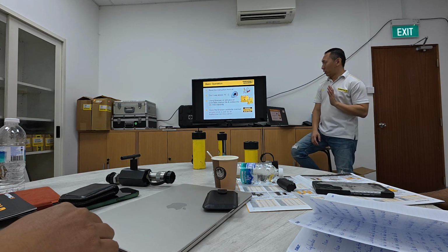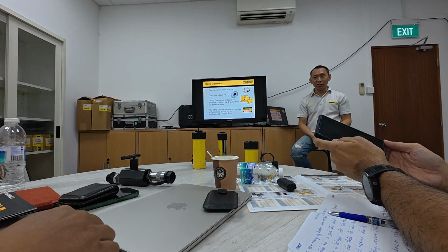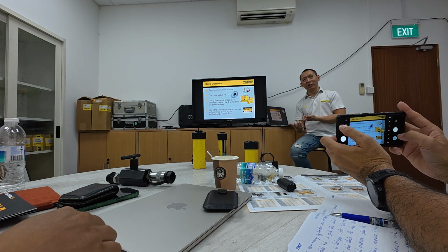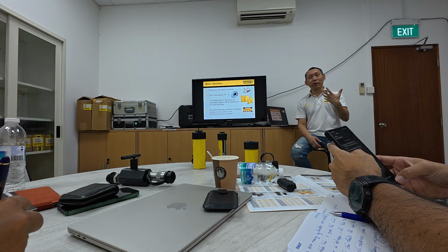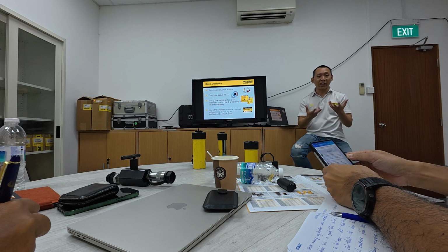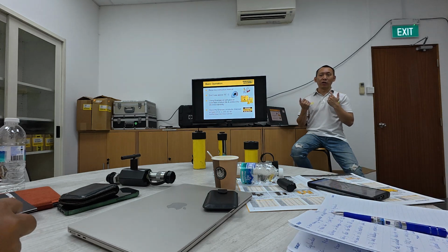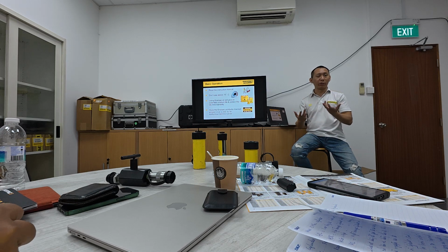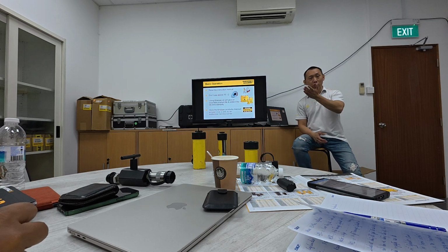Why so? The reason is if they use another type of oil, we cannot guarantee the performance of the oil with our product. Different grades of oil might have different compositions. Some might have corrosive content, some might not. We don't know how it will react with the seals and the materials in our product. But for our ENERPAC oil, we use ENERPAC oil to test our product, so we can guarantee that it will perform to the specification.